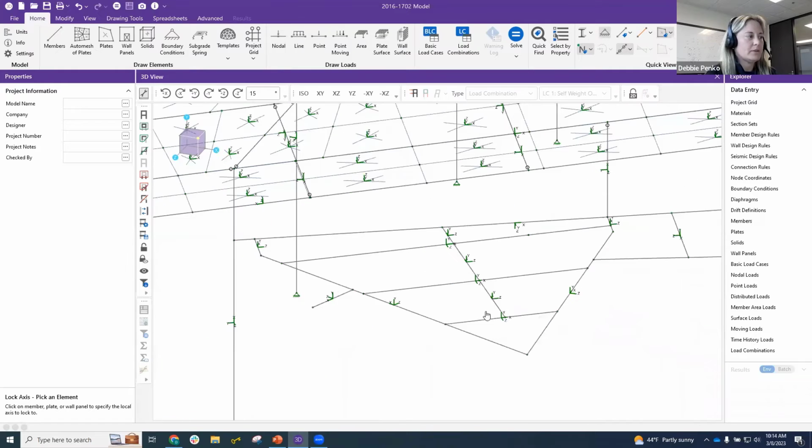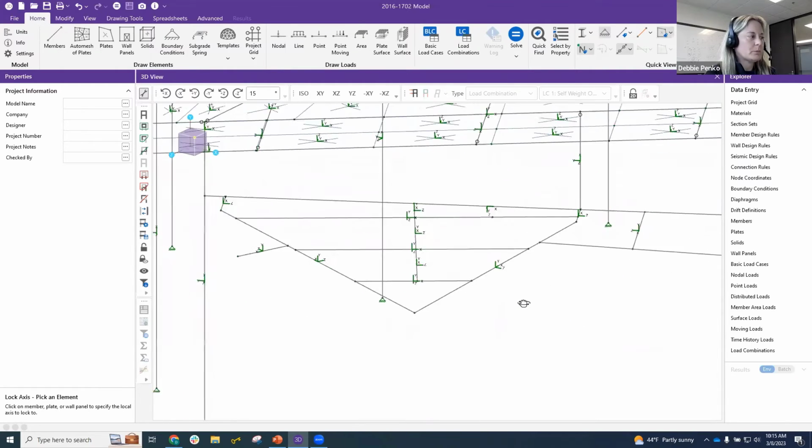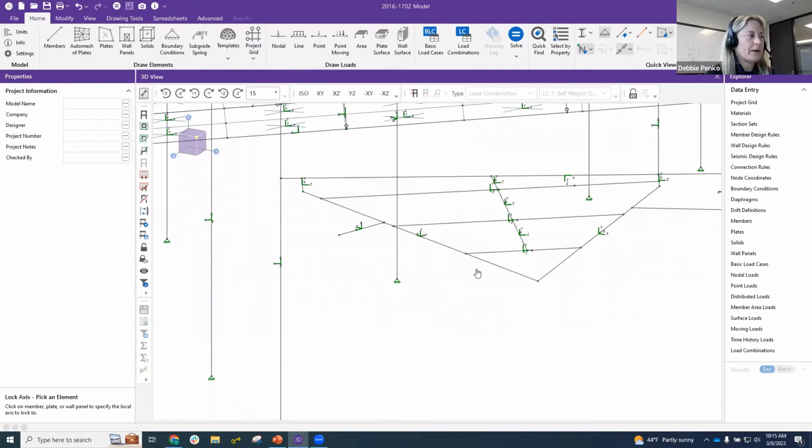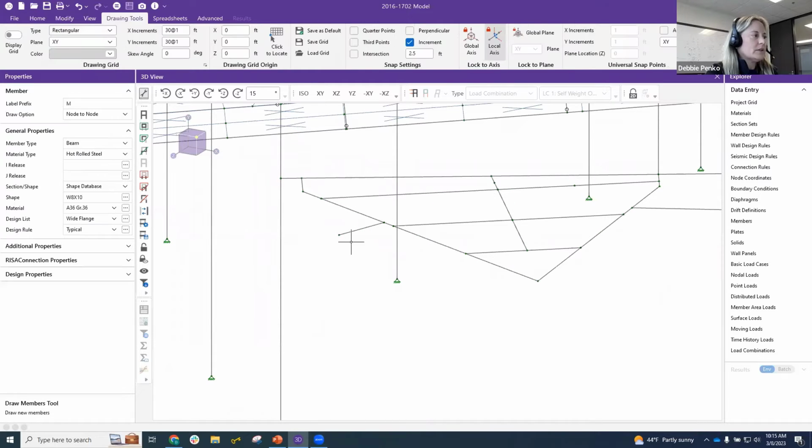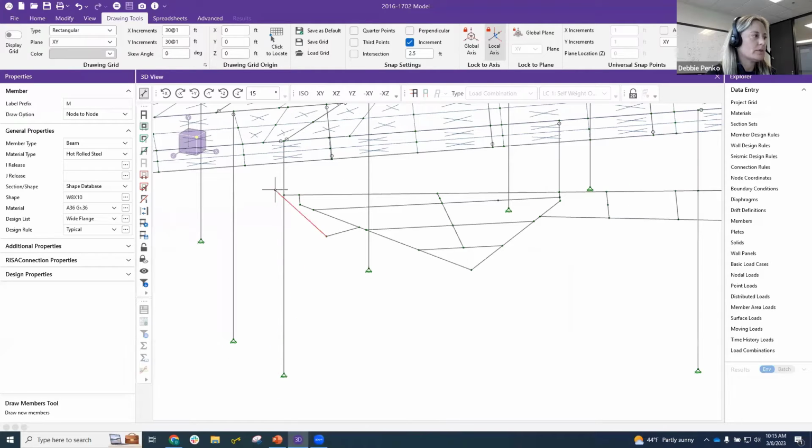Now I escape that, and you can see it lets me draw a perpendicular increment off of that. I can keep drawing things, like we can draw this back to a certain point on here. For example, I know I want this column, currently I hover over 11 feet. So I know I want to maybe hit 8 feet, but my little increment is hitting me at 7.5. So what I want to do is do a straight 8 foot.